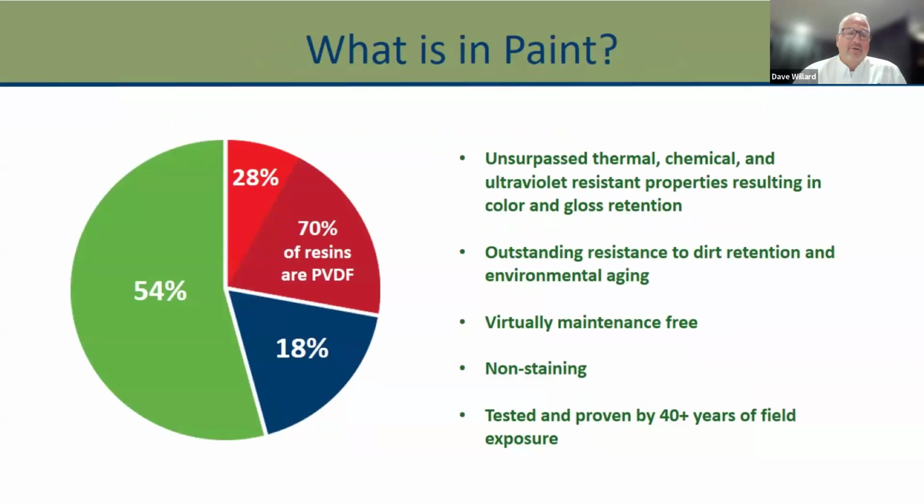Now, the paint nowadays, the technology has changed a lot. Its resistance to ultraviolet properties keeps its color longer and retains its gloss and color. It has outstanding resistance to dirt and environmental aging. It's virtually maintenance free when you talk about the PVDF paint finishes, non-staining, and tested and proven by over 40 plus years in the field. And most companies now are doing 30, 35 year paint finish warranties when we talk about PVDF.